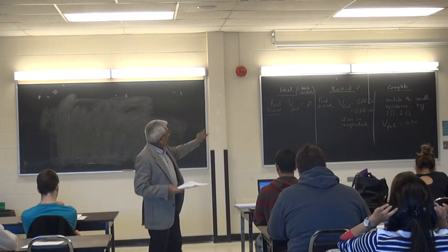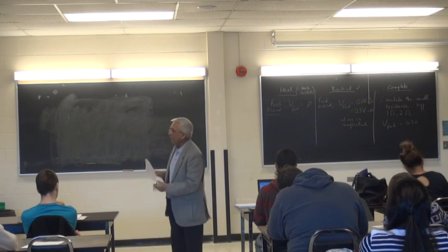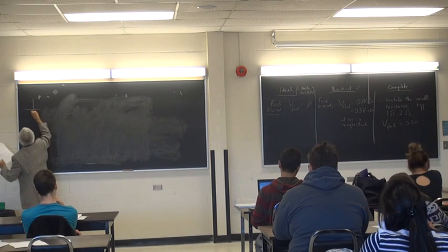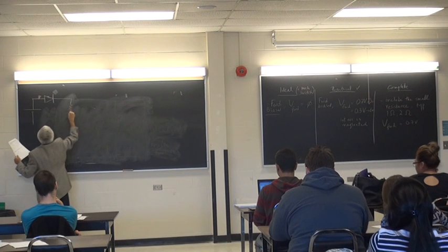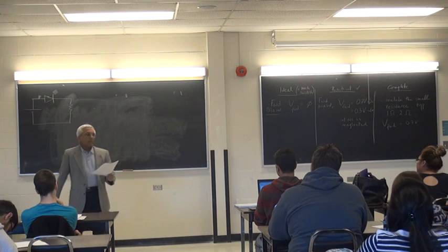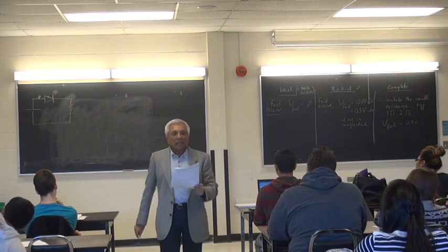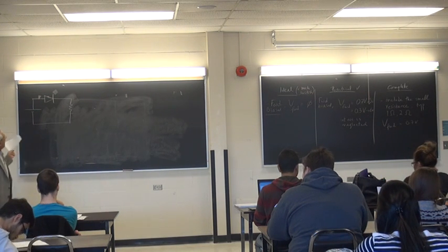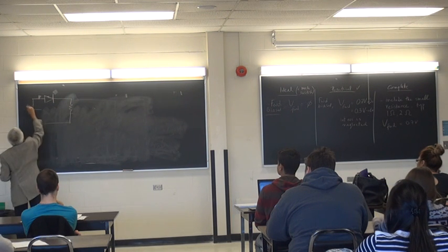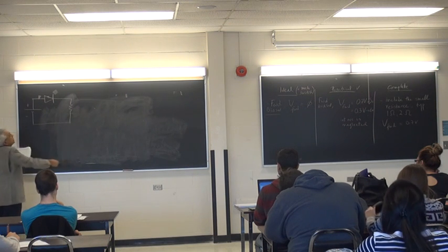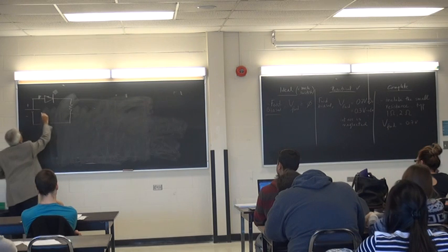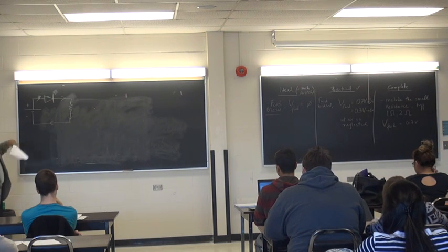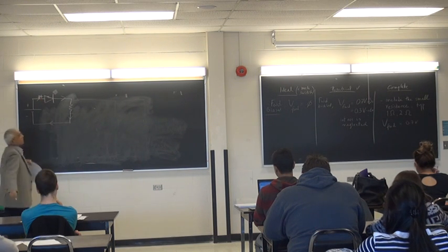All right? So with all this in mind, let's quickly go over number 3 and number 4 one more time, which we already have. Go to page 2. Number 3. In the circuit diagram, label A for anode, K for cathode at the diode. The first thing I do when I look at a diode circuit is identify the polarity of the diode. So as far as the diode goes, current flows from the plus of the supply to the minus. So I identify the plus and minus at the diode. Where the current comes in is plus. Where the current comes out is minus.